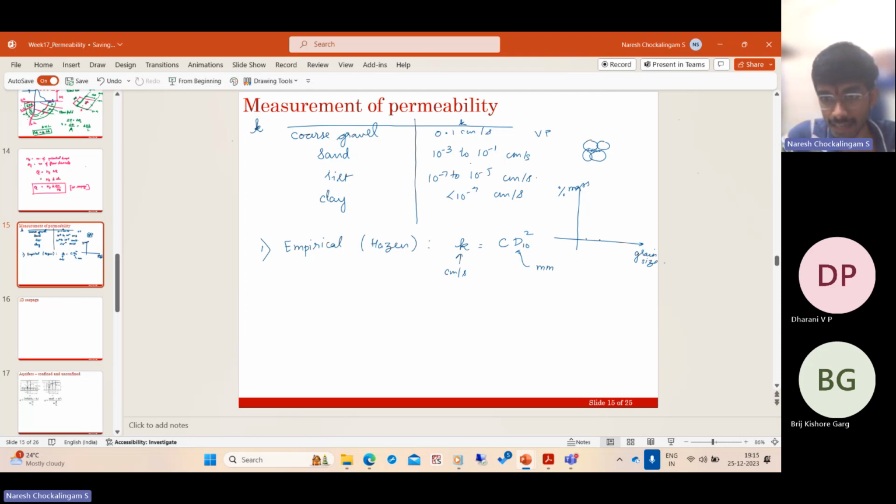As the grain size increases, more soil falls into that range, so typically you have a sigmoidal distribution. Now corresponding to 10%, what is the size of the particles that is not exceeded by 10% of the soil? That comes around here, and this value is D10.